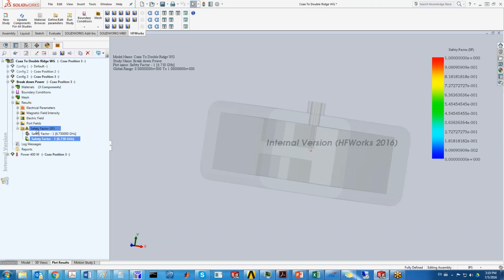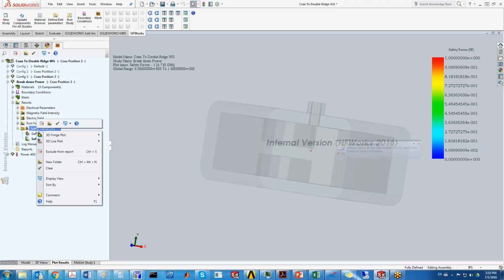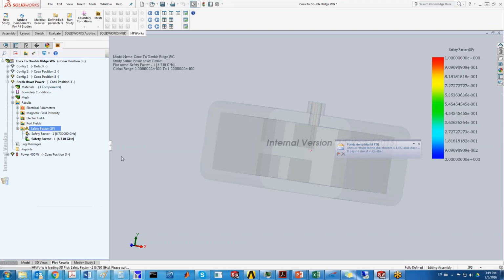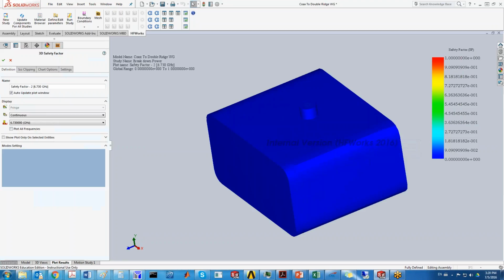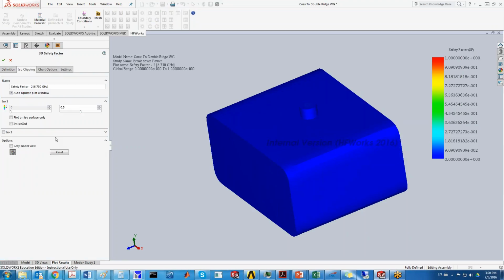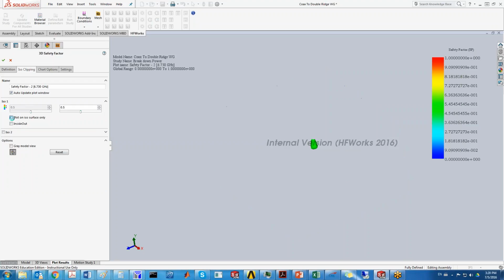By the way, regarding an isosurface, maybe I can show you how this is done. If I do an iso clipping, I can plot the isosurfaces only, but of a certain value. So this is a safety factor of 0.5. Where am I at 50% of this level? If I want to go lower, where am I at 0.18?